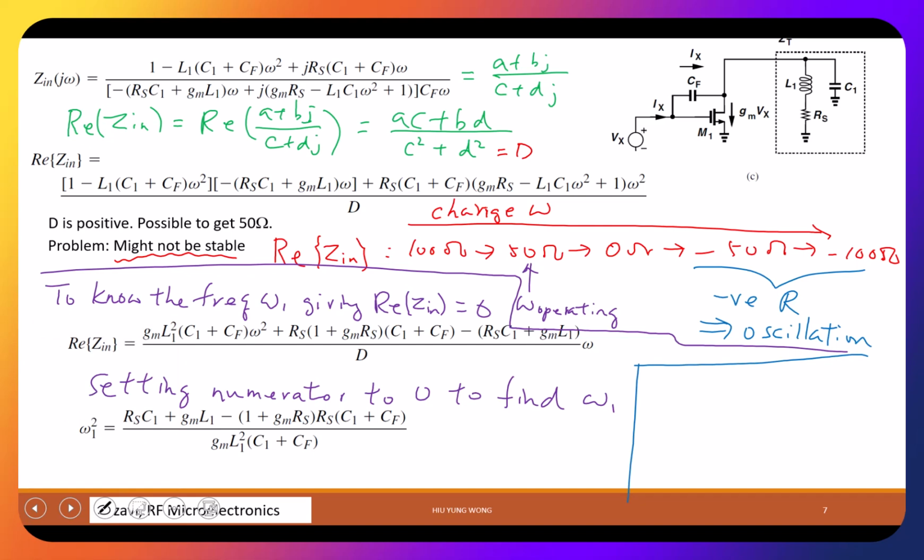Why do I say that? Because the impedance of a capacitor equals 1 over j omega C. This is equal to negative j over omega C. So you have an imaginary part that is negative, just like a capacitor. And for an inductor, it's j omega L. So again, this is positive j omega L. What value doesn't matter because effectively it's just a number.